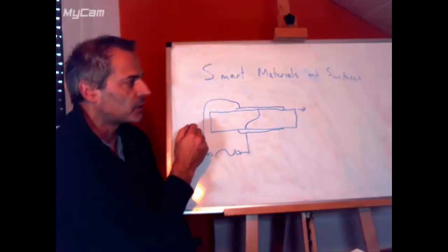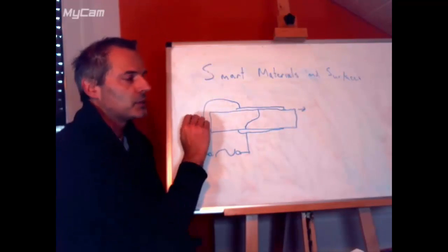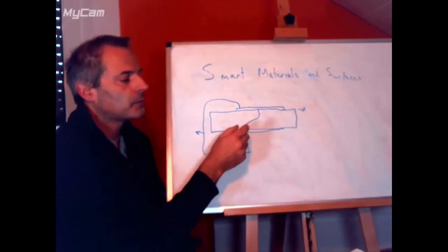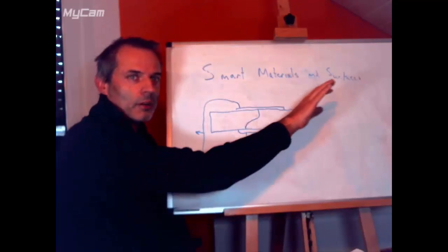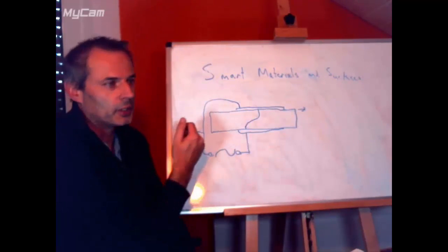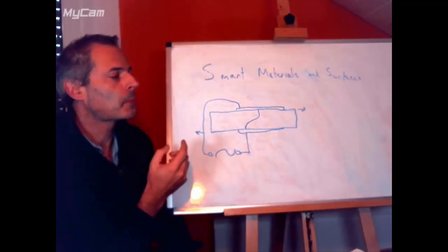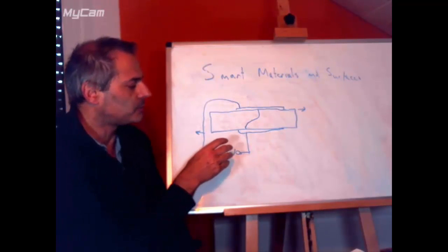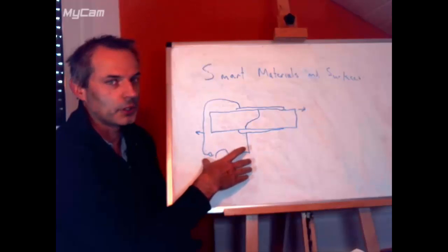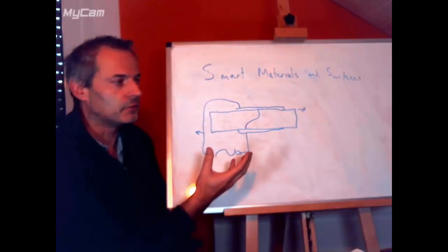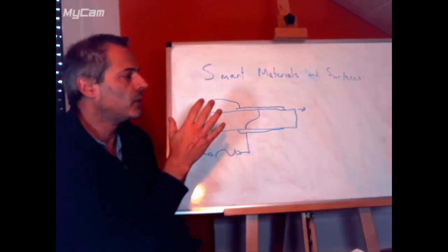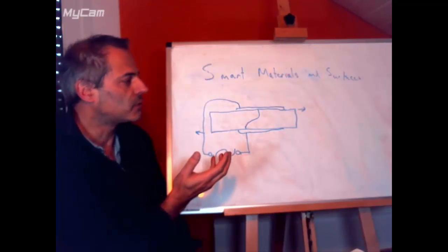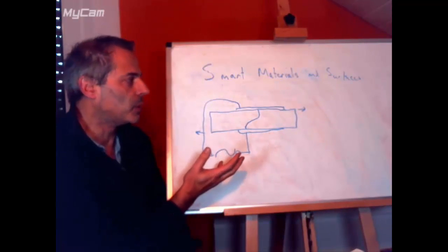And if it's faster, then we'll try to come back, but it's still wanting to move further because it's carrying on moving, so we're actually powering against its momentum. So there are frequencies where this will oscillate better, the resonant frequencies, and that's what we're trying to find with our watch. We're trying to find a resonant frequency that we can then measure.